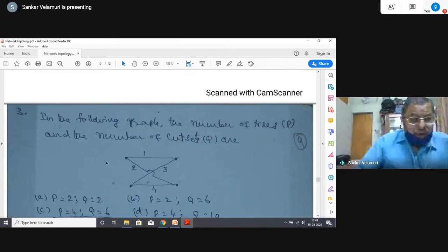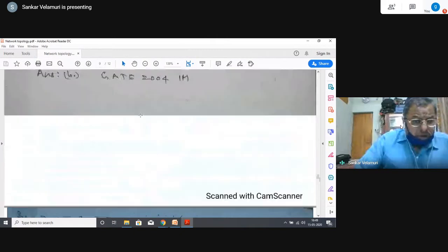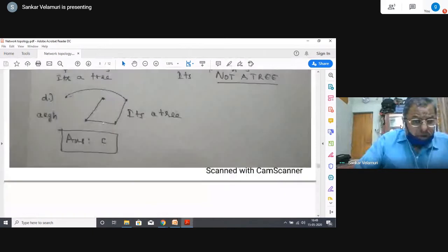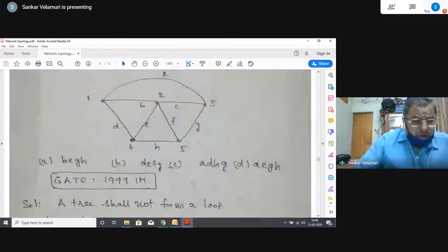What I meant to say here is, for this particular vertex under consideration, 1, 2 is a cut set, and 1, 2, 4 also is a cut set. In the sense, this node and this node are getting isolated if 1, 2, 4 are deleted. If 1, 2 is deleted, only this node. If 1, 2, 4 is deleted, this. I mentioned this in the earlier problem. It's very critical, right?